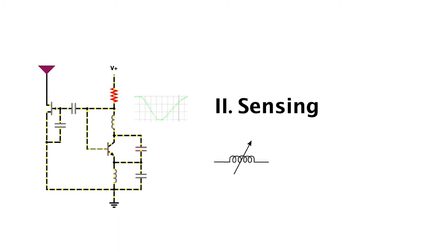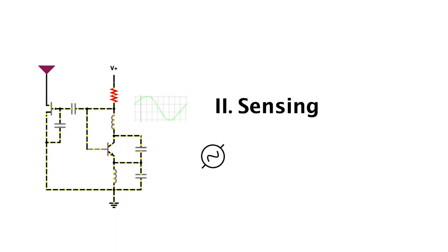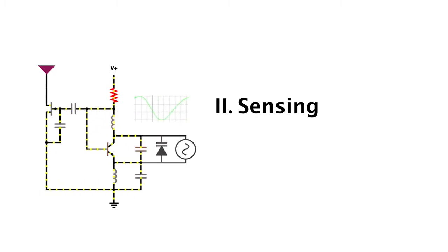Inductive sensors could be placed in conjunction with L1 to modulate frequency, while capacitive sensors in conjunction with C1 or C2 to do the same. Finally, voltage-based sensors can be placed by C1 or C2 along with a varactor to translate voltage changes to capacitive ones.